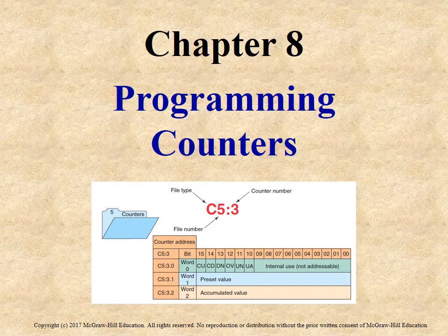They're very closely related in the sense that the addressing works pretty close. The only difference is that we're not forced to use a C5 or any of that nature. We can call them counters or Joe's counters or Fred's counters, whatever we want to call them. But in this particular case, they show us the C5:3, which is the 500 version of the counter.